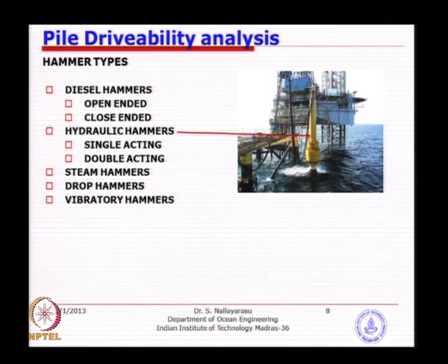Before going to the pile driving formula, I was looking at hammers, which we will just quickly browse through, various types of hammers, which in fact I have already introduced to you. One is the diesel hammer, the steam hammer, and then the hydraulic hammer. The basic principle of working is similar, except that the driving fluid is different. For example, a diesel hammer is a typical diesel engine which has a cam, so that it can rotate, which will translate into a linear motion. The linear motion will lift your cylinder and piston up and down, and basically the movement derives energy by lifting a heavy weight, which we call the ram, and just lifting it off and leaving it down.